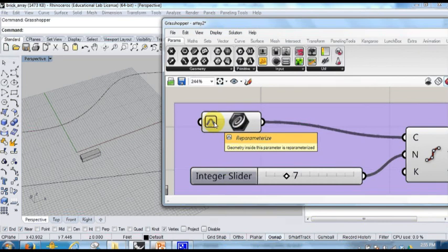In a linear geometry, like a curve or a straight line, you only have one value, right? It's a one-dimension value between 0 and 1. That value is actually a t value, right? It's a t value between 0 and 1. So 0 is the start point. 1 is the end point. So if I give you a t value of 0.5, which point is that? It's the center, right? The midpoint along that curve.